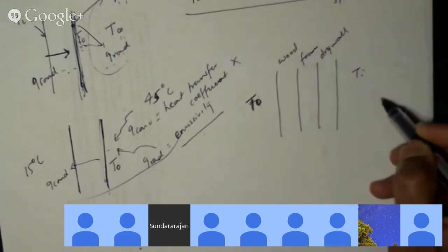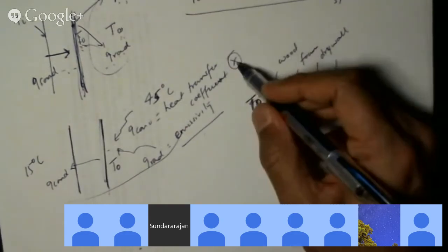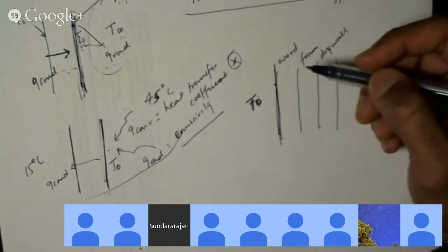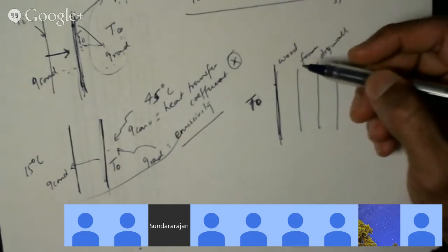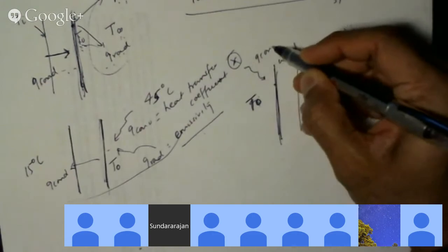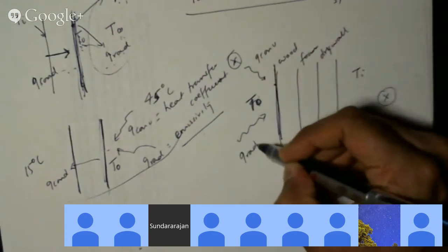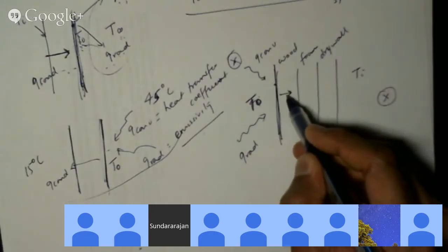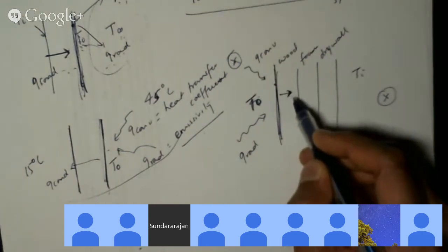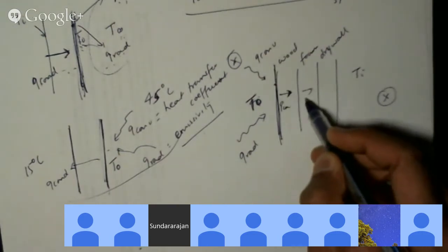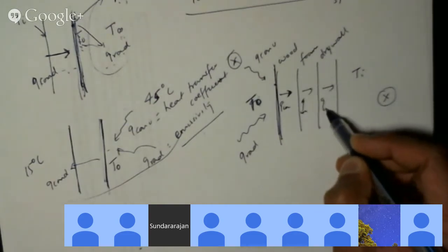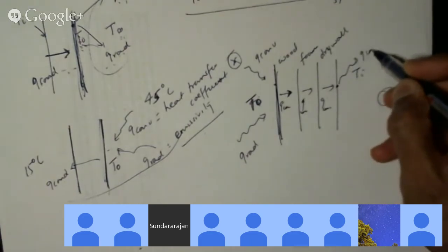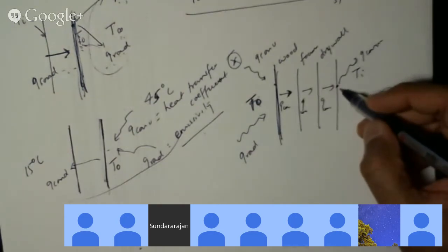How is the heat going to go from here to here? This is the outside and this is the inside. How is the heat going to come from the outside to the outside wall? Through convection, and then radiation. And then it's going to be going through this first layer through what mechanism? All the way through. Conduction, right? And then once it hits this wall, now what? Convective. And then if there's an object that it's going to radiate, then radiation.